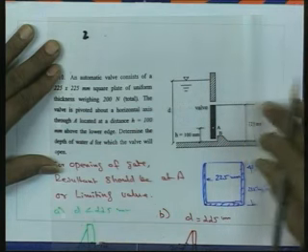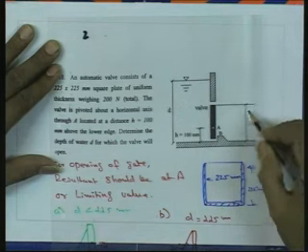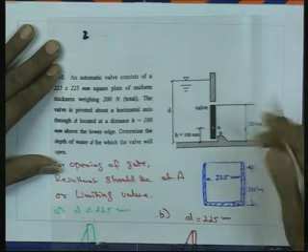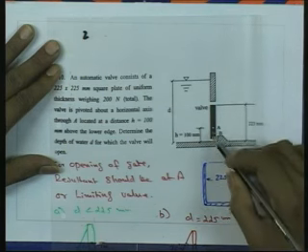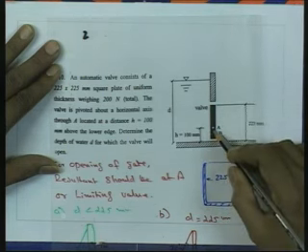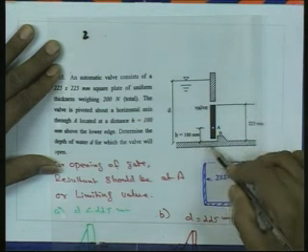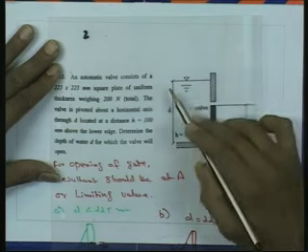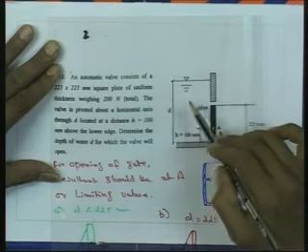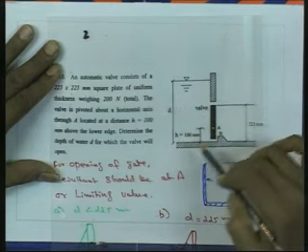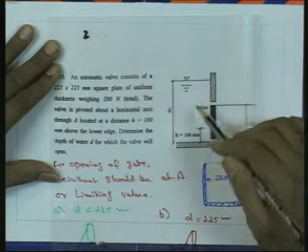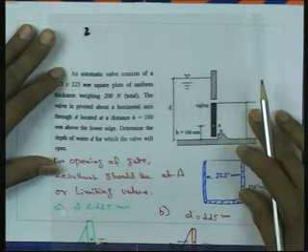Here there is already water depth of 225 millimeter on the downstream, and the valve is pivoted at h is equal to 100 millimeter from the bottom. We want to find this depth D, the minimum depth for which the valve will open.